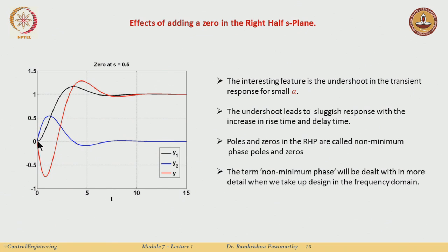But what I am doing is, initially if I just switch this on, I see that I am actually going away from 0, which might mean, well, I just want to stop it over here, because I think the system is doing something very weird, right. But then if I just let it go for a little while, it reaches the minimum here, and then it actually starts going up, and then does something same as the previous one, that there is some increased overshoot. Of course, the response is a little slower, the overshoot has increased, and the settling time does not change much.